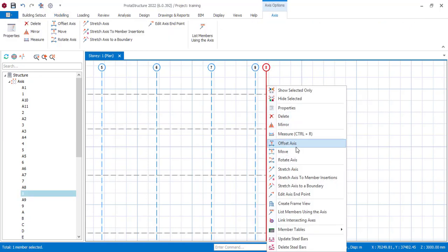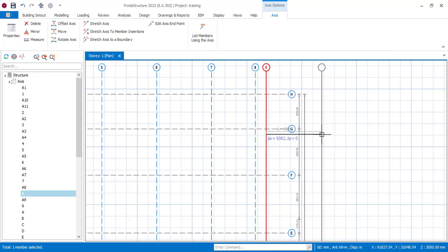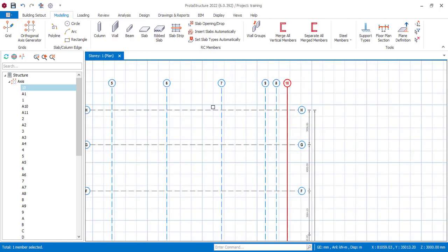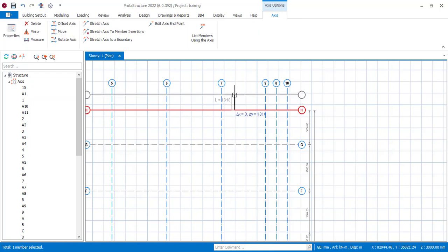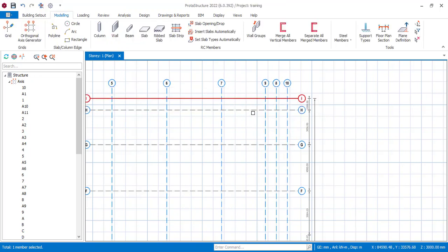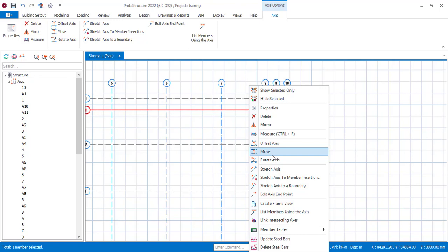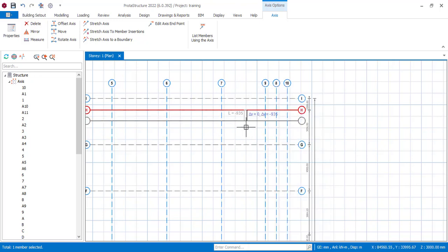Similarly, if I want to offset forward, all I need to do is hold on Ctrl F2 and type 1 meter. I don't need to type in plus, because whenever you are going forward, there is an invisible plus in mathematics. I'm sure most of us are familiar with that. So basically that's how to achieve that when you are going forward. If you are going upward, upward is positive, downward is negative. Going right is positive, going left is negative. That's basically all you need to know about this.